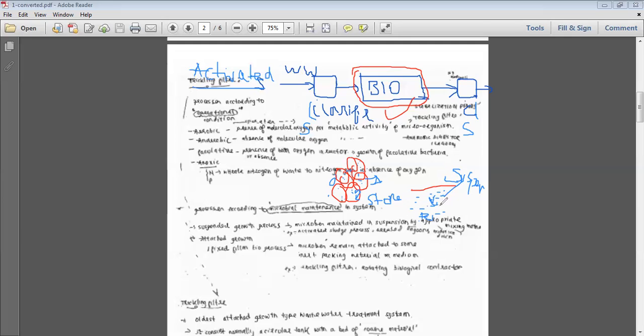Oxygen may be completely depleted, which means as the microbes use more, we have to provide continuous oxygen. So for suspended growth, we will build a tank where continuous air is provided, which is called an aeration tank. There these microbes start growing.